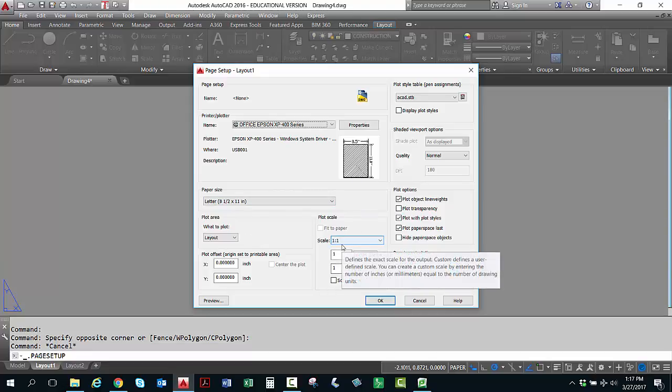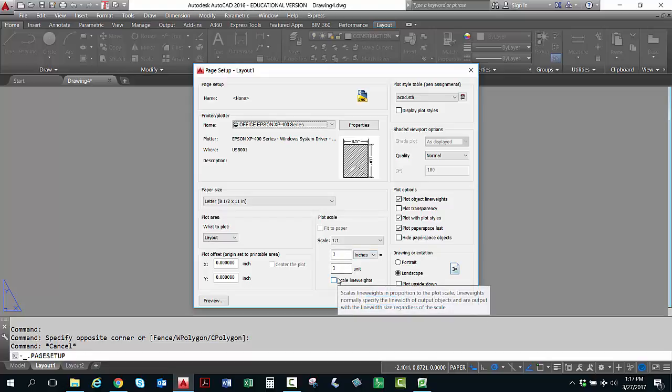Now in your book it's showing metric. It's showing a 1 to 25.4 units. We're not doing a metric scale. So on page 7-10 in your little viewport that it shows, or screenshot, it shows for scale a 1 to 25.4. Okay, so we're not using that. It should say 1 to 1 here. Okay. Now if we selected a different size paper, a metric paper, then it would change here because there would be metric units in the paper size.